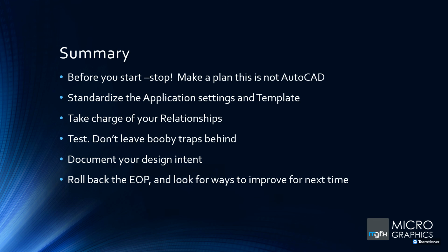Okay, in summary, when you're doing these modelings, before you start, stop and think, make a plan. This is not AutoCAD. This is a parametric package with lots of calculations that you can put in and lots of rules which make sure that your design is on the right track and you get out what you put in. Standardize application settings and your templates. I didn't really speak about application settings, but go into it and make sure that everyone's application options are the same so that you guys are getting the correct materials, the correct template with the correct size arrowheads, the correct size font, etc.